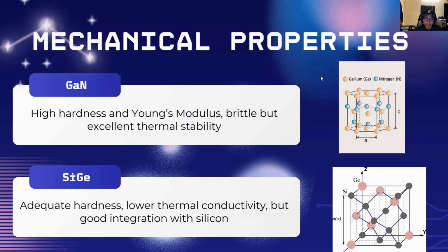GaN nanowires show potential for high power transistors and light emitting devices due to their one-dimensional structure and physical properties. Reduction of grain boundaries in GaN is also an important factor to consider, since the existence of grain boundaries affects electron mobility and mechanical strength. In high quality GaN, the aim is to minimize them to realize